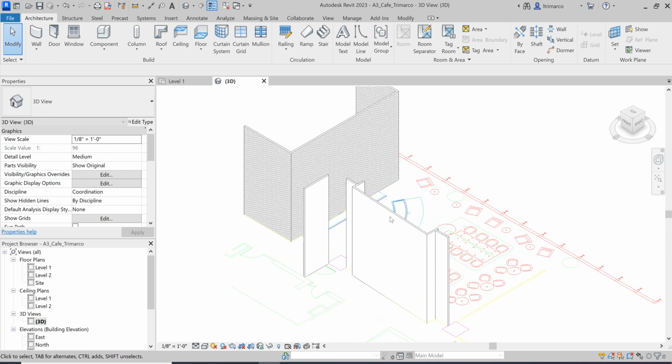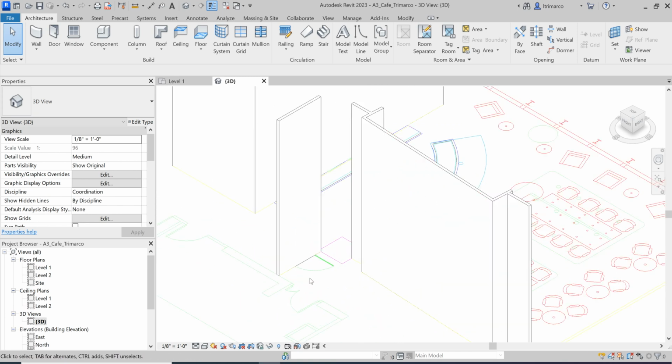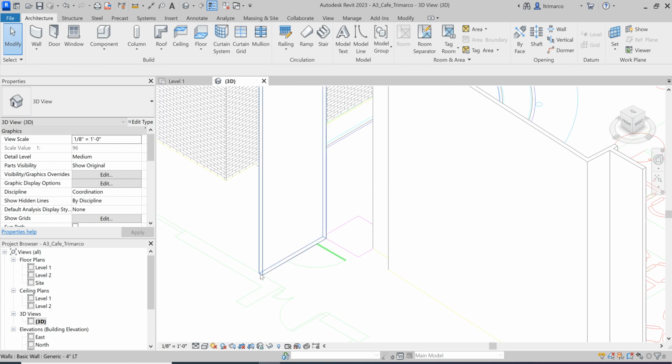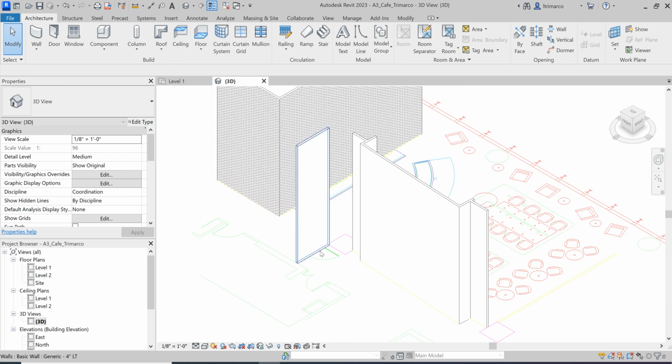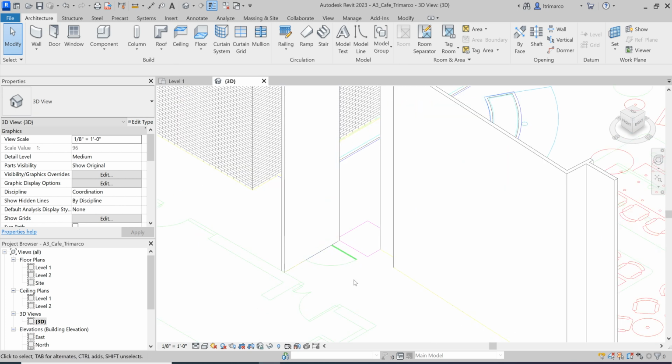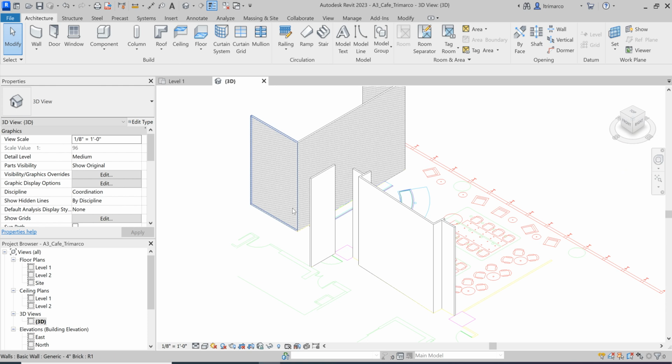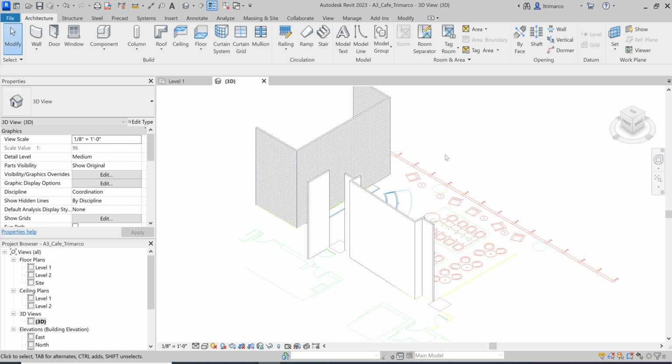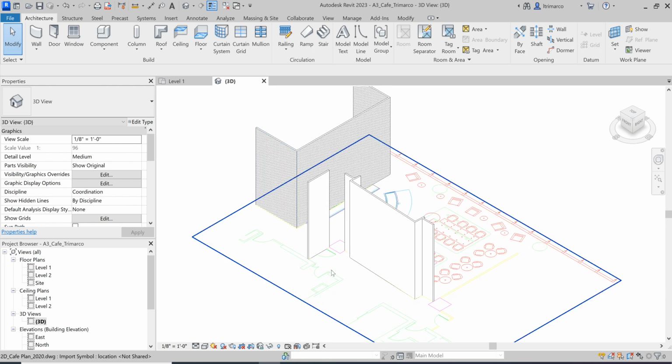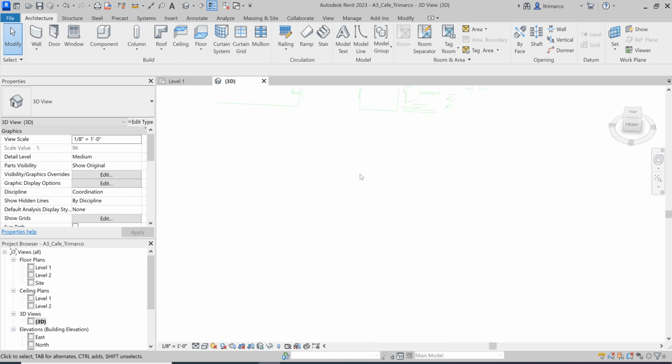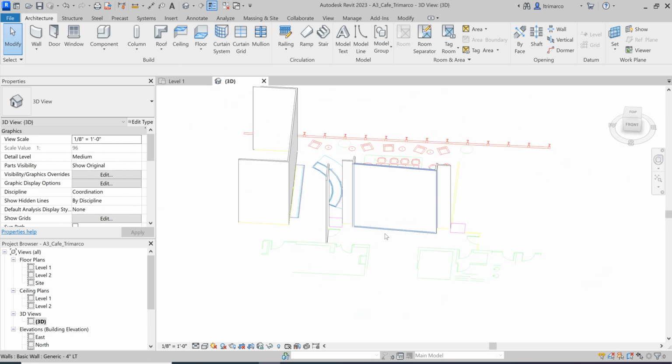I want to point out, as you guys build your walls, anywhere there is a door location, you want to basically build your wall right through that door opening, just like we did in SketchUp, because we're going to be looking at placing a door in the next video, and when we place doors in Revit, they know how to break open the opening. It's part of the parametric building, or I should say the BIM, building information modeling, and it's a wonderful thing to see. So I'm going to let you guys move forward with building the rest of the walls up.